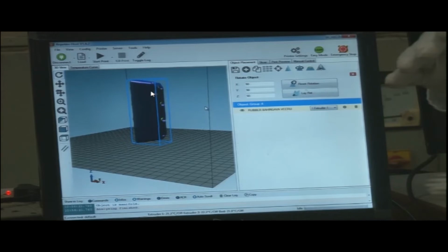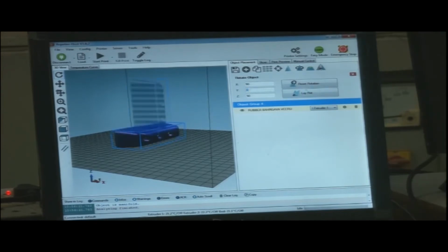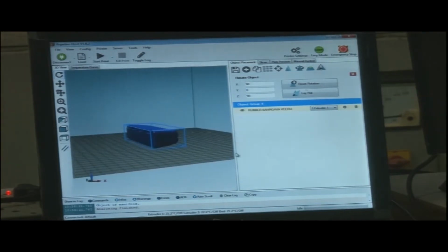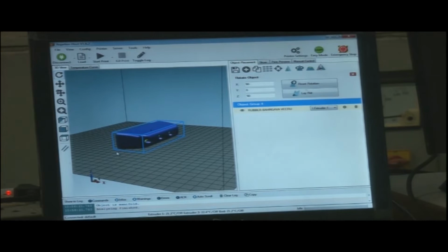Total time means total economy, so the total cost of the product would also increase, because in the product cost function, machining time is one of its factors. So this is not a very good position to manufacture in. So we can opt to select the flat position and orient the job in the proper place and position.